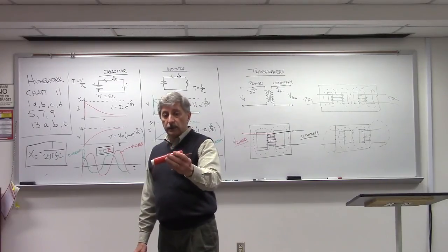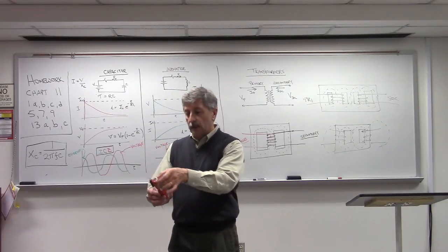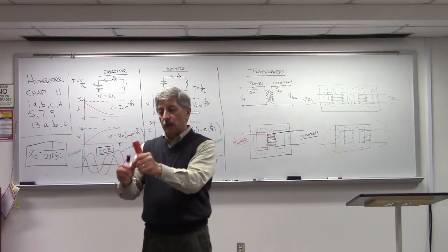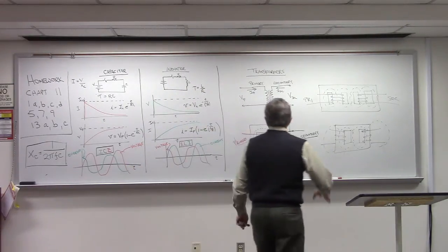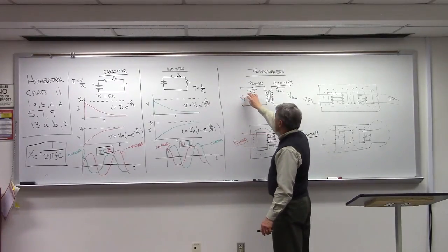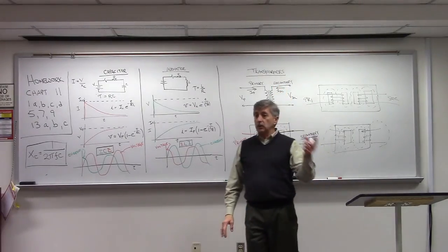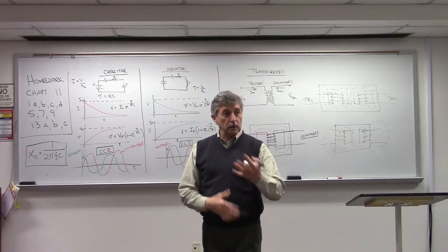I guess I would get some transfer of energy on that guy, but not a whole lot. Technically, this coil ought to be wound right on top of the other one. So as you feed this coil from a source, the magnetic lines of force would cut across the other coil and induce a voltage in the other coil, which would induce a current in the other coil.